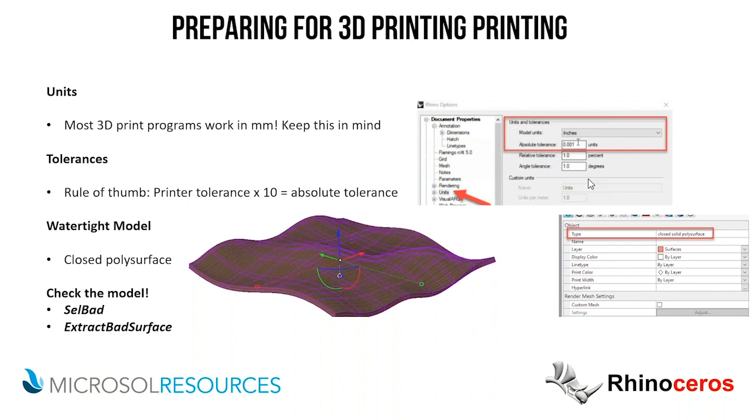And that surface is not going to be very smooth. You're going to have a lot of overhangs. It's not going to be a good surface for printing. So probably the best way to orient this for printing is to print it on one of its sides like this and add a raft or brim in the beginning to support that.